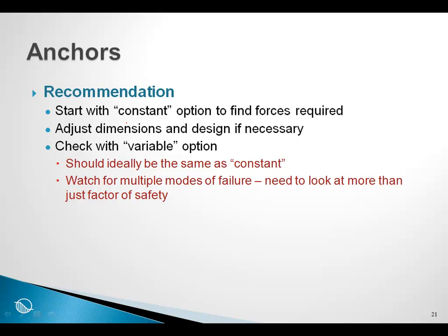But in general, we recommend that when you use anchors, you start with the constant option and try to answer the question, what do I need out of my reinforcement to get an acceptable factor of safety? And in practice, once you know that, you could then dimension the size of the anchor and select the materials for the anchor. And once you have done that, you can adjust the dimensions and the design if necessary.